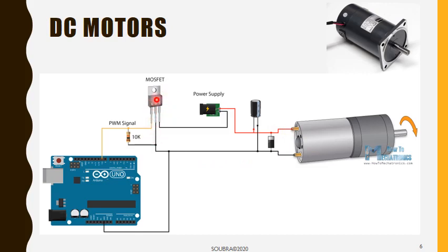How does this particular transistor work? Basically, we have one leg connected to the control pin here. When we apply a 1, we're going to close the circuit between those two, between D and S. And when we apply a 0 here, we're going to open the circuit between D and S.